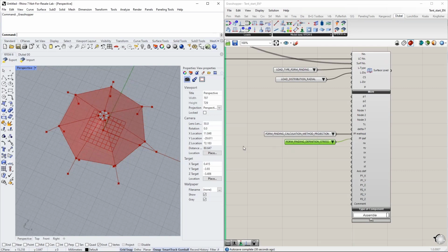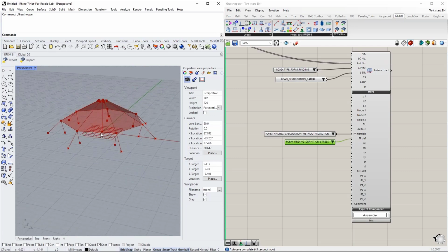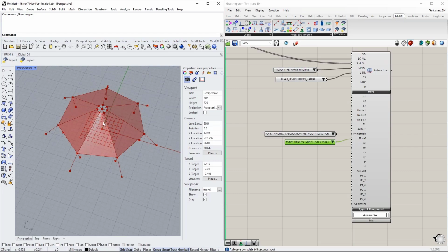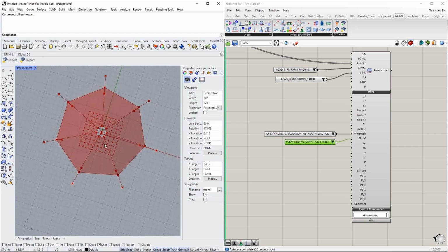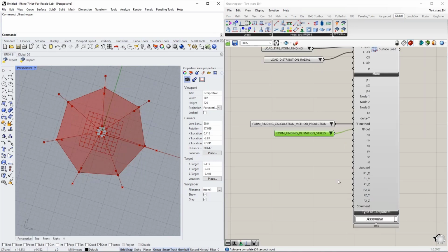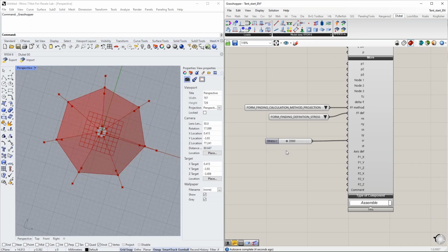With this new load, it's not required any longer. I can simply say I have a rotation axis, let's say upwards, basically similar to my center column. And then the load knows, okay, tangential means this one, radial means this one. So what I have to do now is first of all define the tangential and radial stress in Newton per square meter. So Newton, not kilonewton. This is what we expect here as SI units.